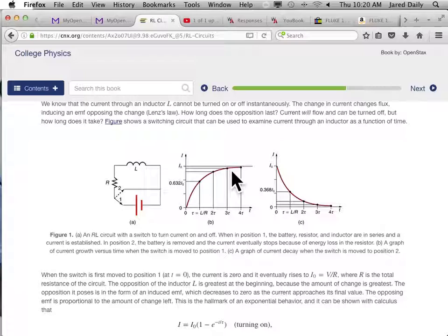So they're really weird things. A capacitor kind of behaves like a wire at first. Current goes to the capacitor at first. But then as the capacitor starts storing that charge up and it can't store any more, it starts to behave more like a wall. And then it behaves like a cut circuit where current can't flow anymore because it's full. The capacitor is full.